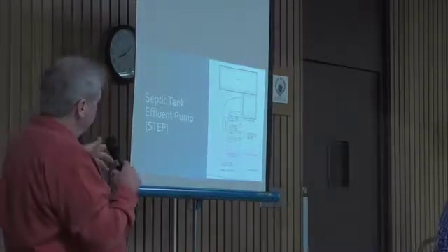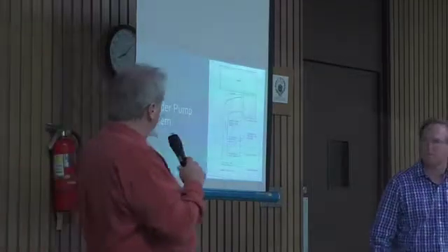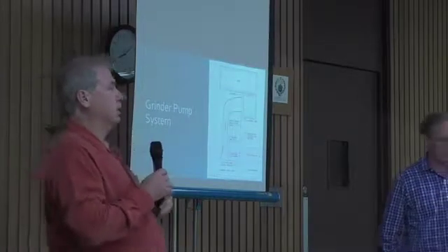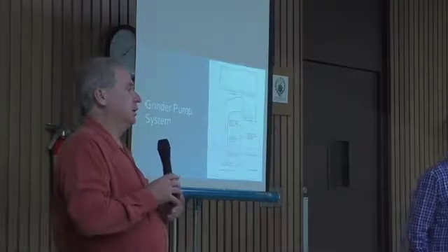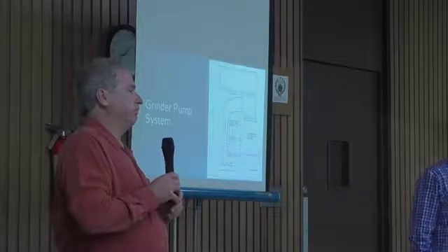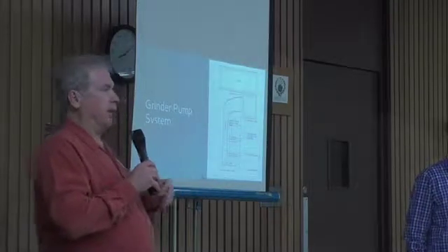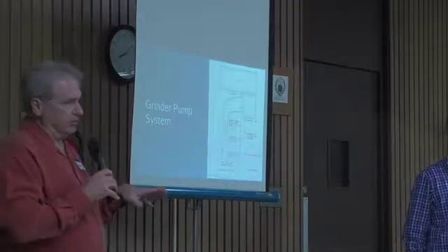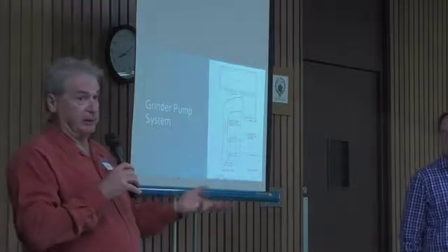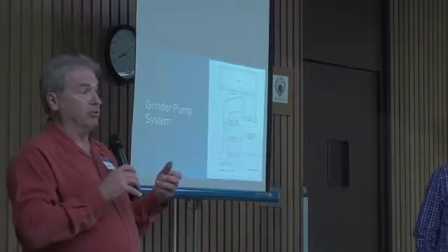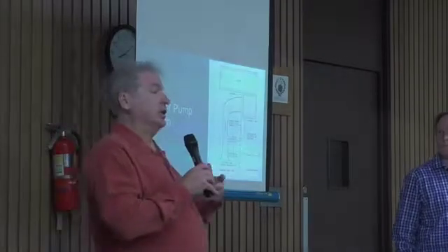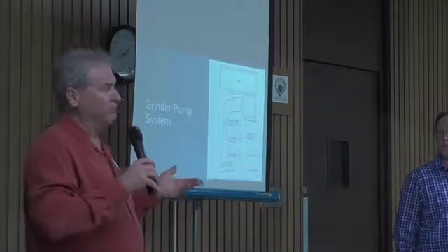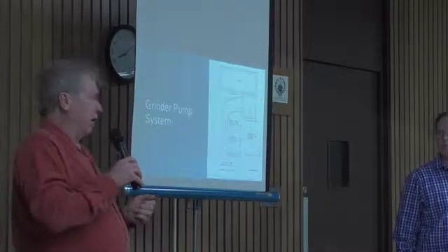So the other system is a grinder pump system where we're... Before you leave the STEP, the state will not finance a STEP system. So it's off the table. We had another project where the state basically said, look, we just don't want to consider it, because another disadvantage of the STEP system is that you have these septic tanks in every property. And so the state's concern is you have a potential of that septic tank leaking into the groundwater, and then the whole point of the project is kind of lost.